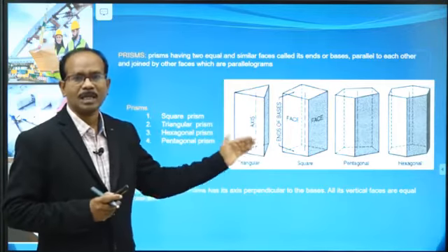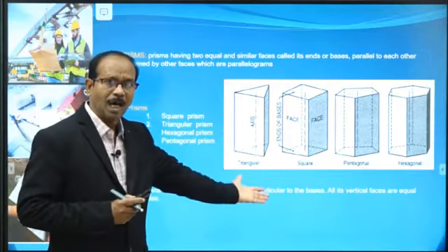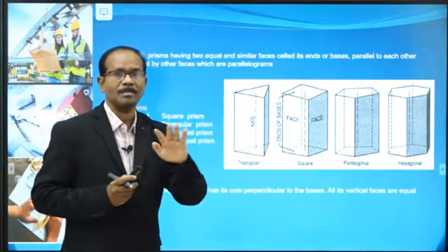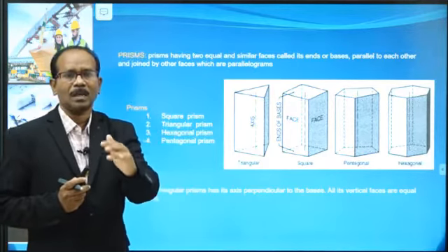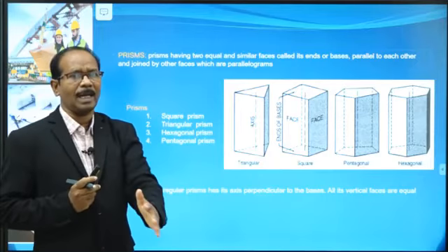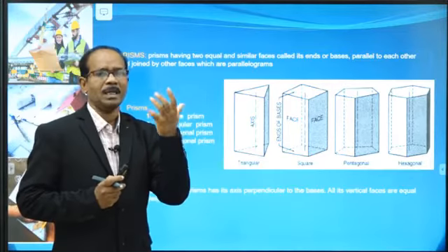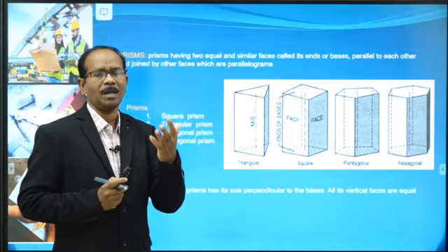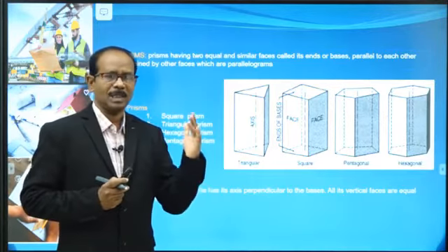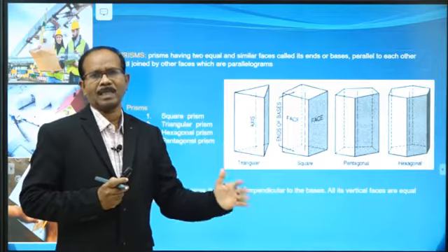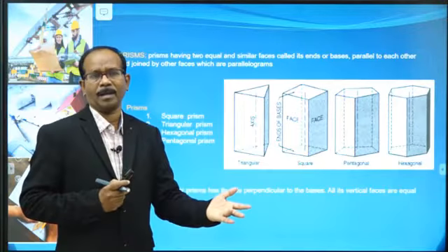The meaning of that dotted line: that line is behind the object and is not visible. Hidden edges are represented with dotted lines. Read again the line table, types of lines: thin line, thick line, chain line, dash line or dotted line.